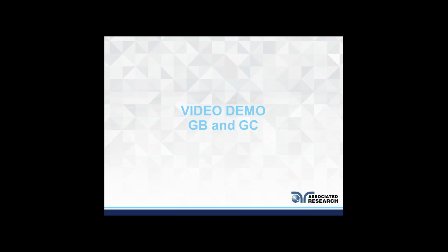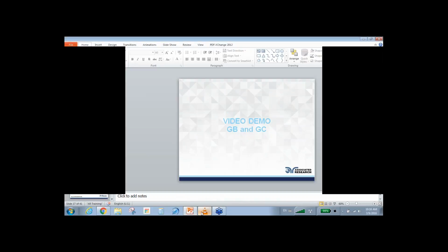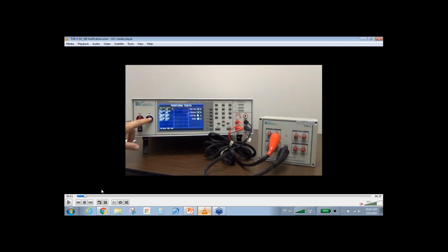I'm going to quickly show a demo of what we do for a ground bond test with our Omnia tester. This is a video that shows us using what's called a test verification box. It's the TVB2 box that's on the right. Basically it acts as a load, and it creates some fault conditions or some pass conditions, to make sure our testers' pass and fail circuit detection are working properly.